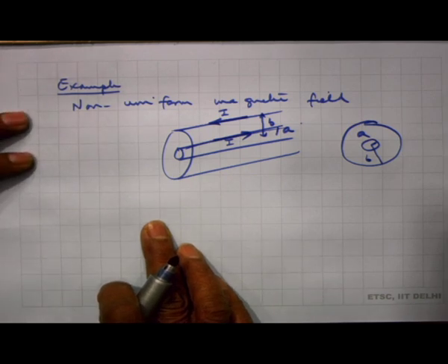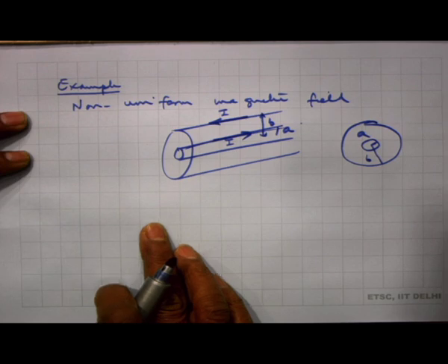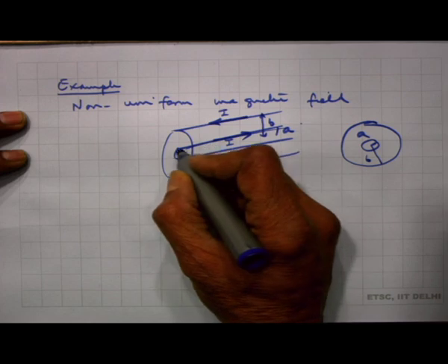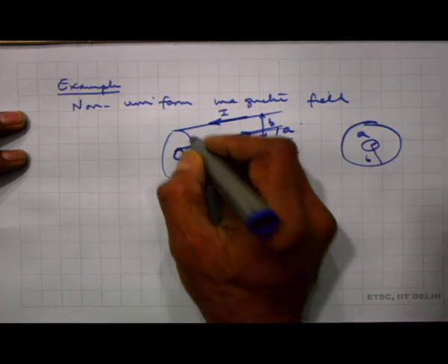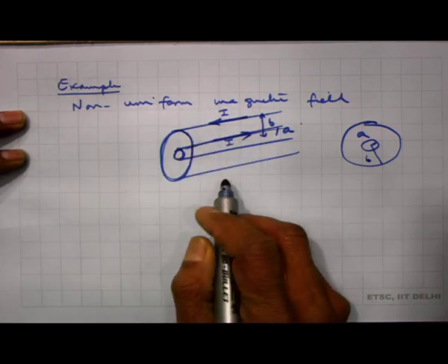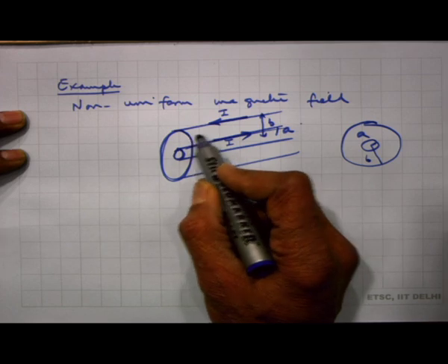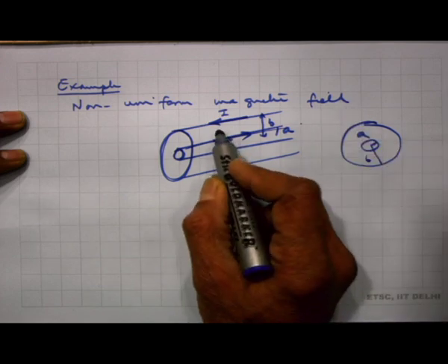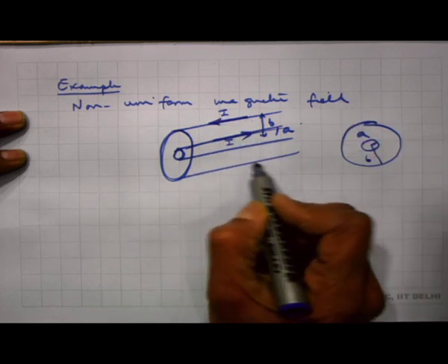So, for all this I need to calculate the magnetic field in the system. Now, this is a surface current propagating through the outer surface of this inner conductor and the inner surface of the outer conductor here. First thing you can notice is because of symmetry, magnetic field will not be dependent on the position along the length of the conductors. Magnetic field cannot have a radial component.